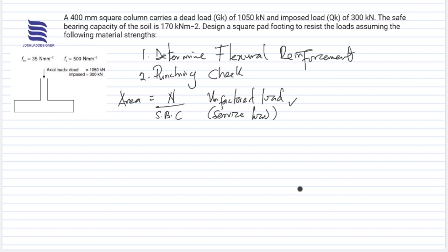But because the idea of foundation design in this case, to obtain the area of this pad footing, we are supposed to use the service load. So you have to find your way down to the point where the service load will be applicable, and that's just the idea.